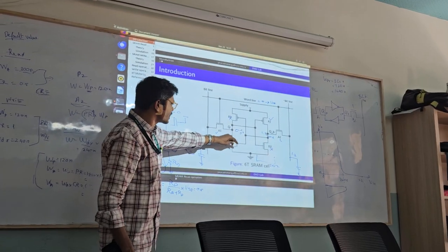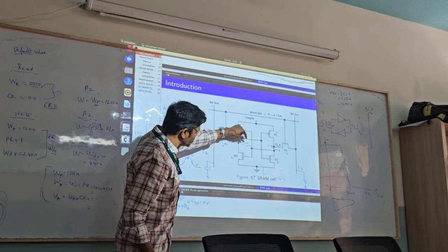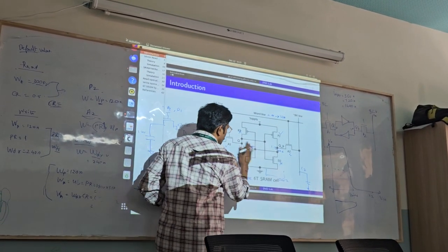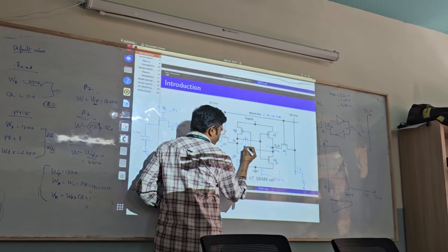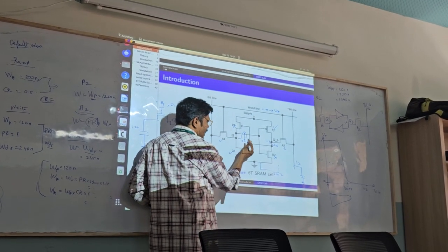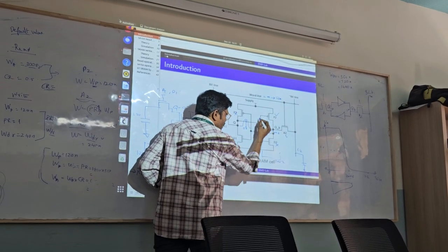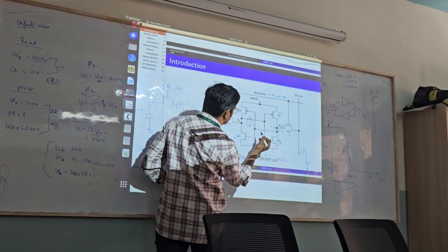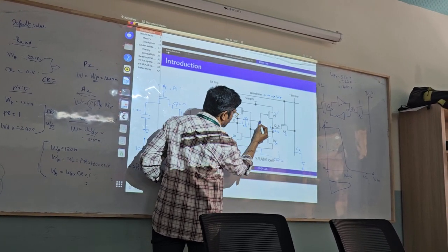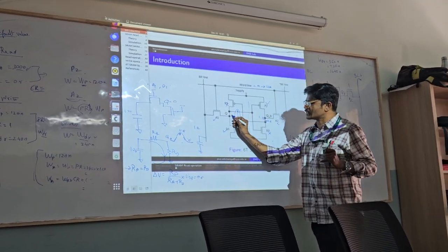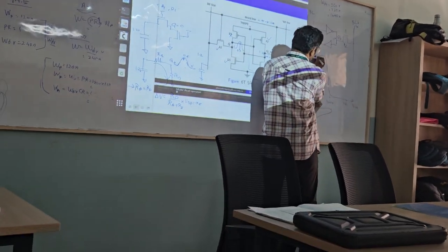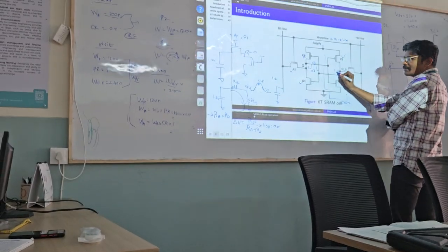From the voltage transfer characteristic graph, when I create a bump across this Q node, because of this peak value of 0.6, this is being applied to the input of the second inverter, and we are trying to analyze it. When the input is at 0, my output is at 1.2.